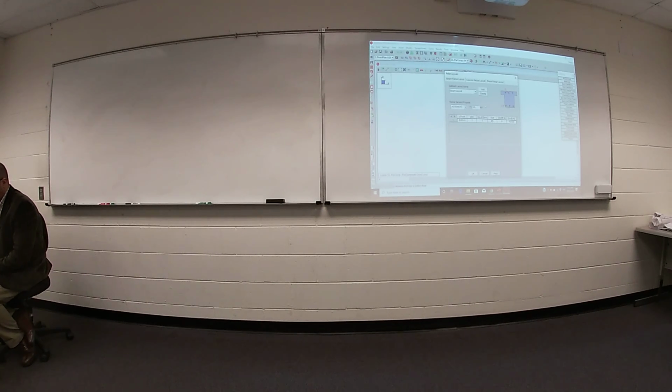So I will start new, add. I will label it by the name Ayman, for example. Ayman will have steel reinforcement with Fy 60. Your bottom reinforcement at depth 1 inch, your cover 1 inch.